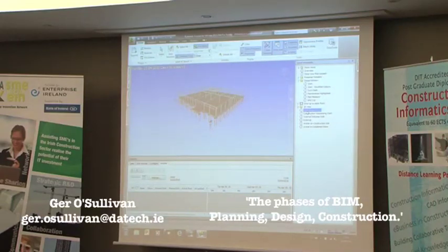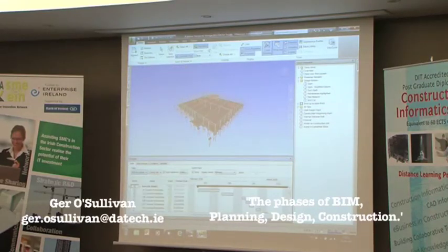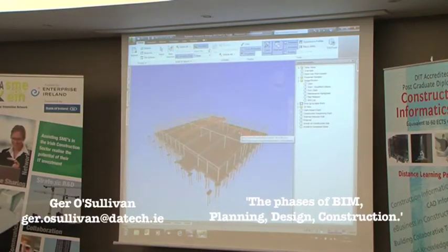And again, another thing that I'll just jump into, and that should finish it up, is the clash reporting, all right? So again, being able to catch clashes before they come on site. Let's just back into my tasks. What I've done in the clash report side of things is, I don't want to be looking at the whole model this time. I just want to look at the MEP side, so the ductwork, and again, these all came from the Revit packages, so the ductwork, the piping, and the structure.